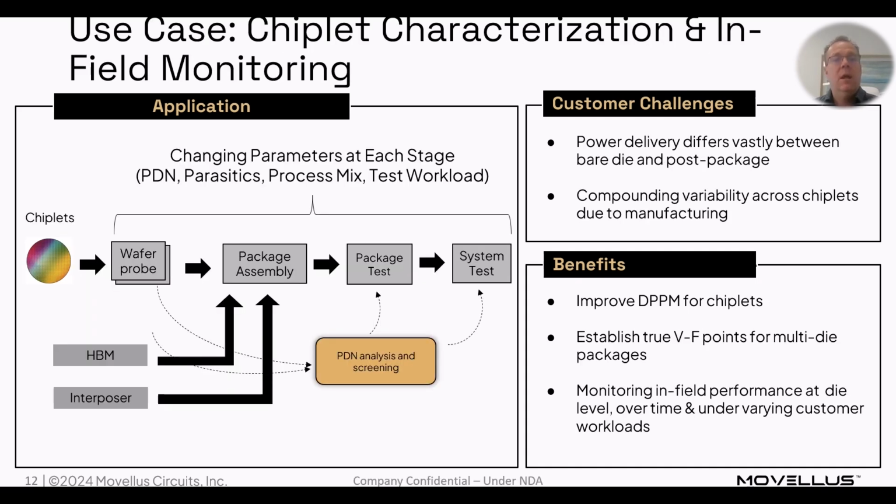So in the chiplet environment, again, having a VF curve at wafer probe time based on the characteristics of the supply power distribution network and the voltages at the transistor. After packaging, having another package device test, having a different PDN, having a different testing environment, perhaps with a socket on an ATE versus a wafer probe card, will have a different VF curve family. At each stage of testing, you will need to have a VF table that is used, and also, ideally, having characterized the VF curve, have continuous monitoring to ensure that it is actually indeed achieving the desired voltage at the transistor. As the process changes, as wafer lots change, you want to be able to gather data and continue to monitor.